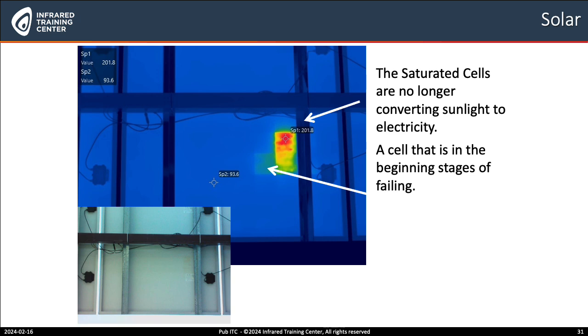And it's interesting because a lot of folks don't realize you need to also check the panels from underneath, if you are able to. Some cells are very close to the roof, like in the previous slide, very, very difficult to do so. But on other panels, if you're out in a solar farm or a solar plant, much easier to get behind those panels. So make sure you get behind them, take a look at what's going on.